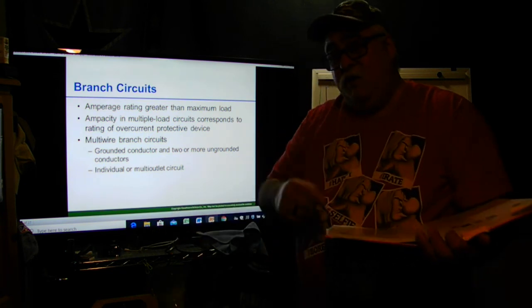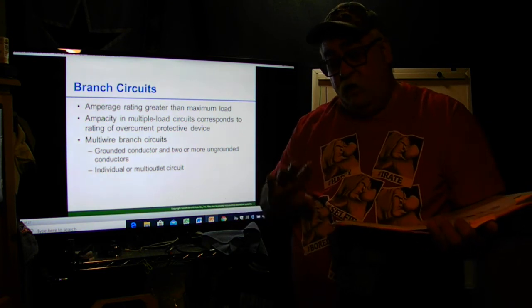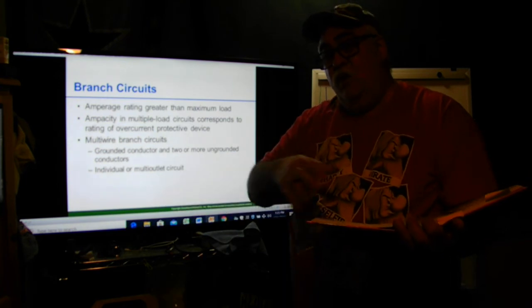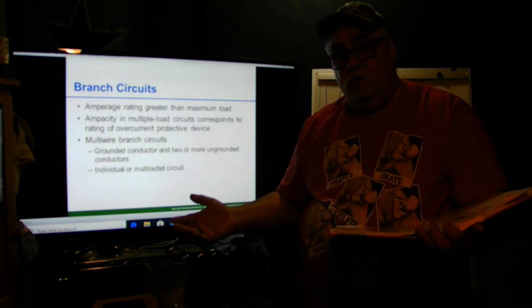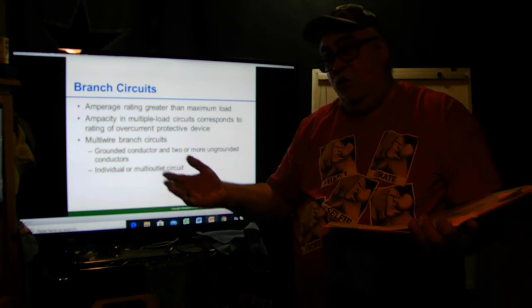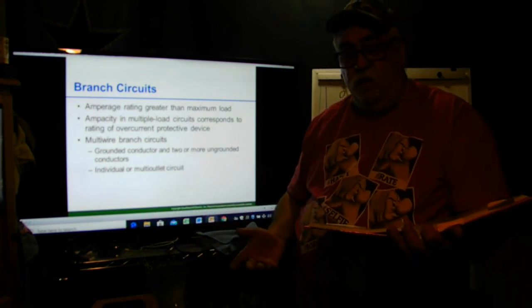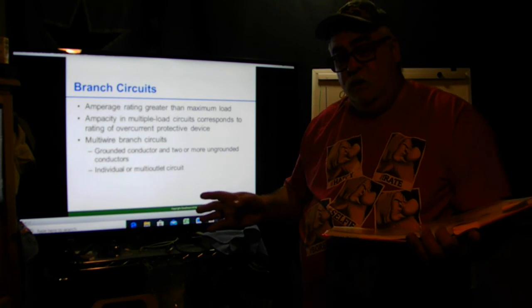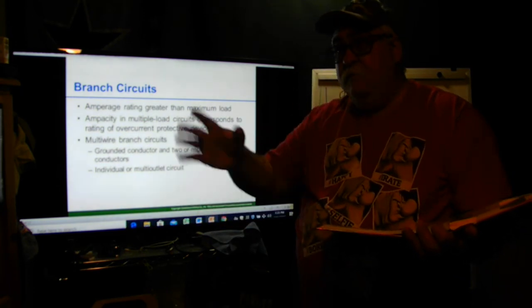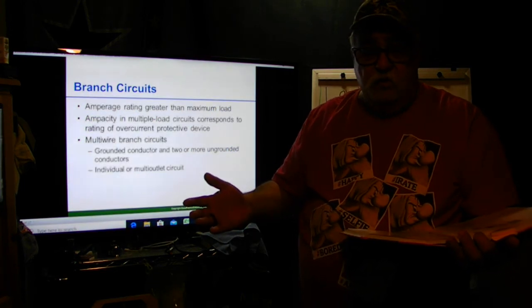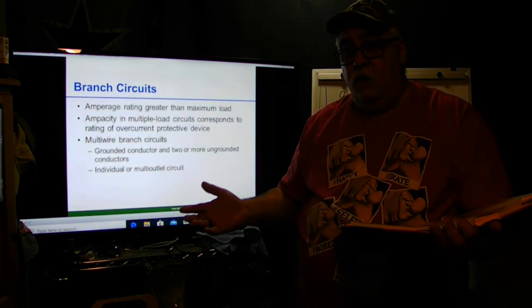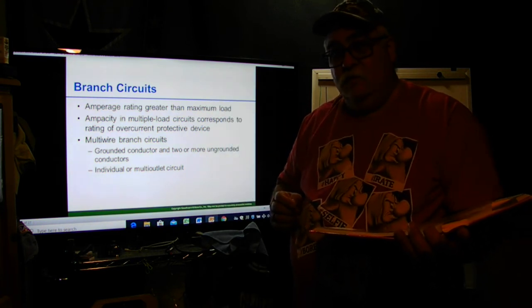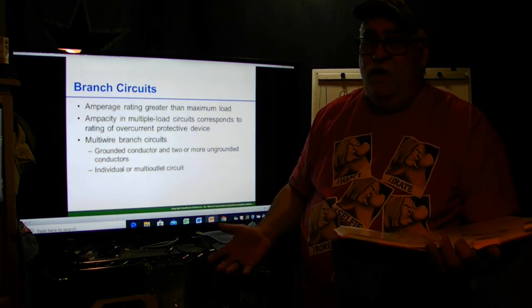Okay, but my overcurrent protection device, my breaker, with my short circuit protection, is not an overcurrent protection, it's short circuit protection. So my breaker for that motor is going to be 250% more than that motor. So I would have a 14 gauge wire. I got 15 amps multiplied by 125%. That gives me just shy under 20, a little bit more than 19. And then a 14 gauge wire can handle 20 amps, the THHN. But my breaker is going to be twice that. My breaker is going to be a 40 amp breaker.